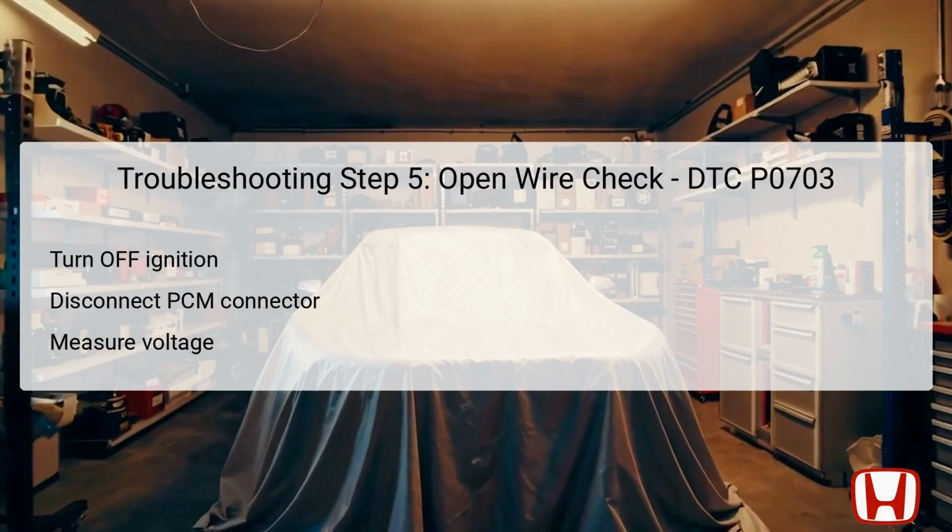Test point 1 is pin 25 of the PCM connector A51P, while test point 2 is the body ground. If you measure battery voltage, the BKSWNC wire is functioning, and you can consult authorized service information or swap the PCM for further diagnostics. If there's no voltage, an open circuit in the BKSWNC wire is indicated and requires repair.